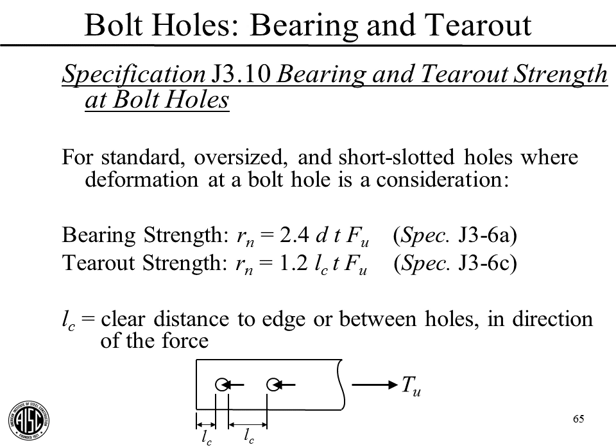I think, and verify this before you run with it, as I'm going from memory here, the extended shear tab design example, I think one of those uses that, and they're trying to get the extra rotational capacity there. But go research that before you run with it. And that's the only time I can think of right off the top of my head.